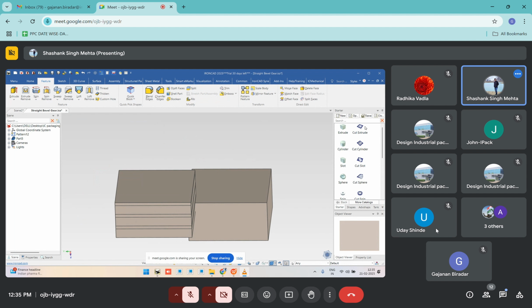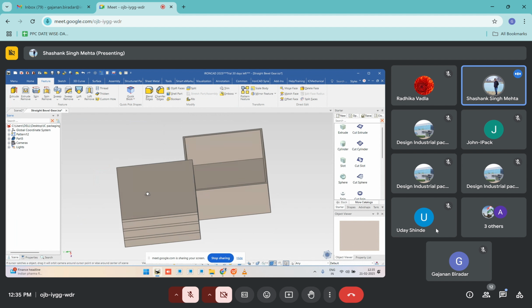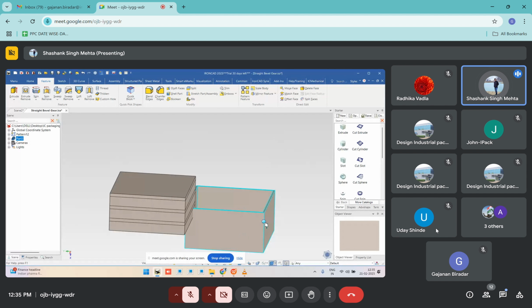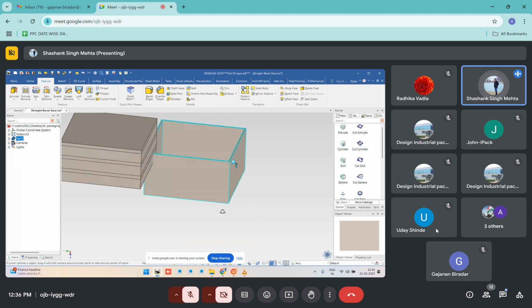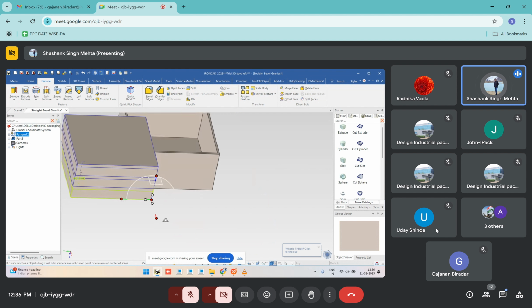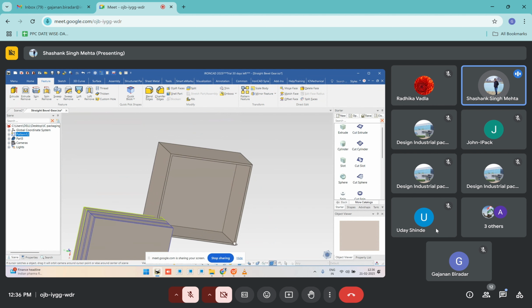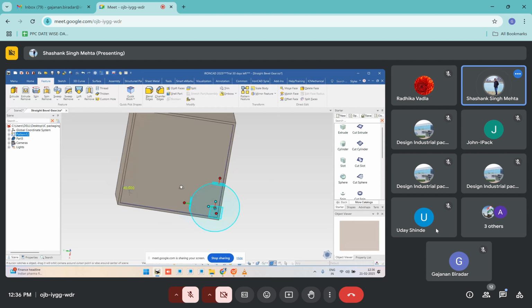feature, right? Feature of our shell part. Directly we can select this surface, right? It to be shelled and thickness, okay, 5. Individual face thickness also we can change it from here, right, to create particular box. Right, so now as you can see, this box has been created. Okay, and we can place the particular pattern in this point. If you want to now place this particular pattern inside this box and place it over to this point like this. Okay.